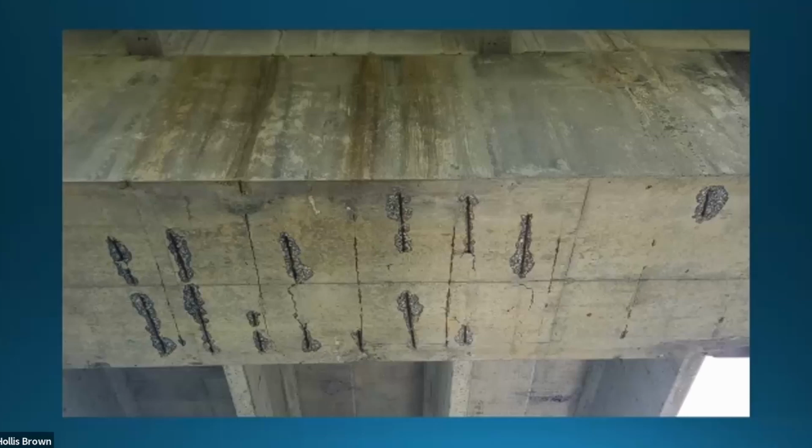But when you put reinforcement in it, concrete starts out as kind of steel friendly, but the alkaline and acidity in it changes over the first 6 to 10 years. It goes from being okay with steel to becoming corrosive as it sets. And then once that happens, like you were saying, the steel starts expanding. It can expand up to 6 times its original thickness, and so it starts breaking out the concrete.